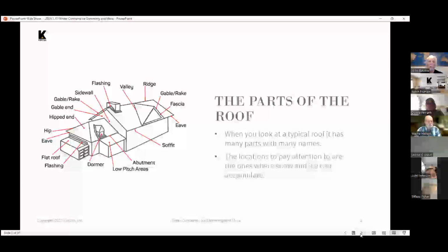If you have the roof elevation changing, then you have a gable end, and the edge of that at the roof line is called a gable or a rake. The wall is the sidewall. At where the lower roof and the upper roof meet, there is flashing installed there. It's called step flashing, that keeps water from penetrating at that location. You can also have dormers, chimneys,